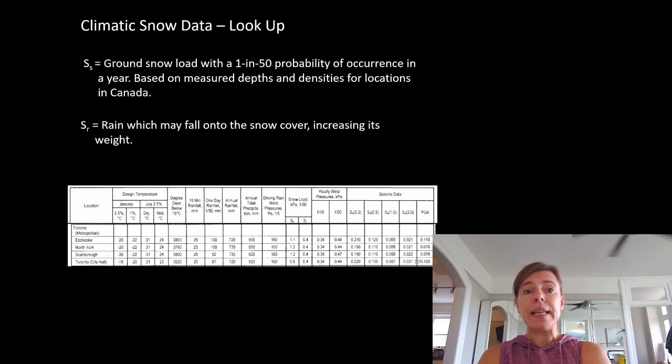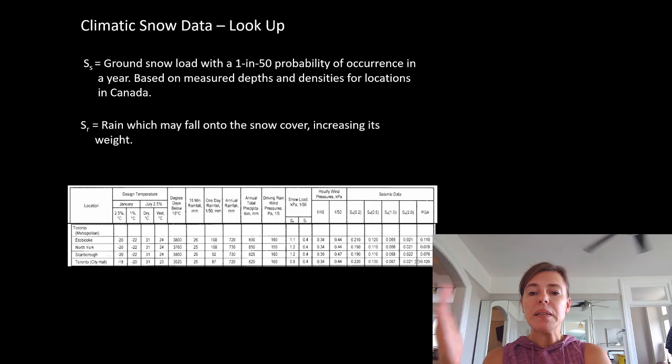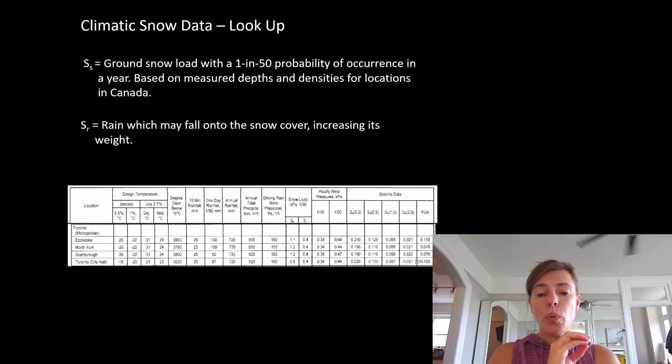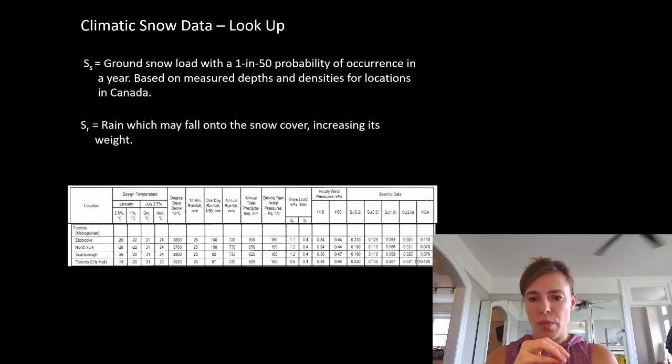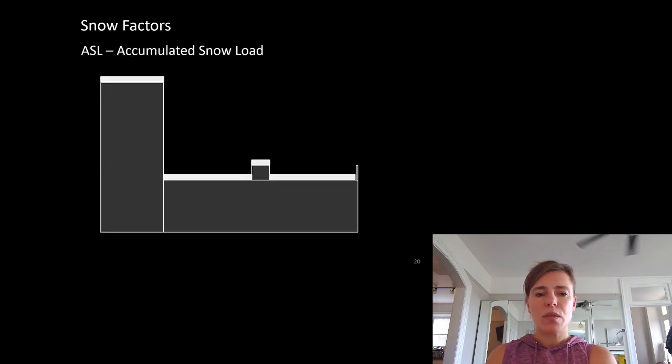But luckily there was damage to buildings, but no loss of life due to collapse of buildings, which means there's something we've done here that makes our roofs stronger than that alone. And that's what we're going to start to talk about in a few minutes with load combinations and reduction factors. We build in some extra safety there because we might end up worse. These are just about statistics, remember. We want to reduce the risk of loss of life. Making everything zero, it would be too expensive. I always say too expensive to design for the apocalypse, but we can get as reasonably close as we possibly can. So let's go back to that.